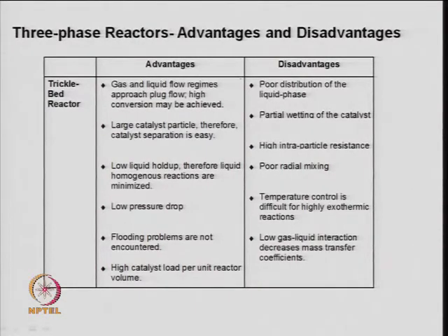So, definitely the conversion will be high. That is the advantage, that high conversion can be achieved in the case of a trickle bed reactor if properly designed. A good hydrodynamic study needs to be done, and the conditions properly optimized, and then one can achieve plug flow design conditions in a trickle bed reactor. So, distributor design is again important in order to achieve high conversion, to avoid maldistribution.